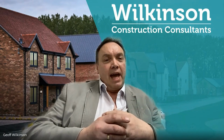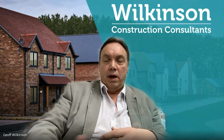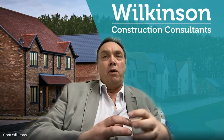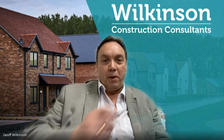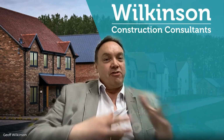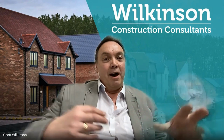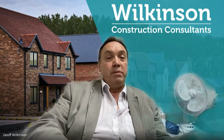But we've even had issues in the past with fill, for example, on sites. I remember working for one local authority years ago, and literally the road was called Brickworks Lane, or very similar to Brickworks Lane, and that gives you an idea of some of the history of the site. So when they actually started digging down on this particular site, and it was only for a domestic rear extension, they found lots of broken brick rubble for the first metre, which had basically been spill waste from the brickyard itself, dumped into this area of land.